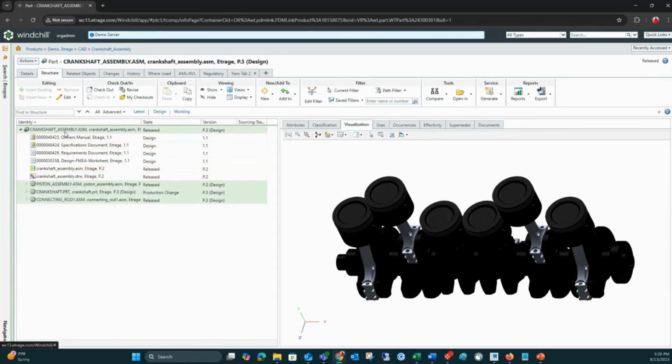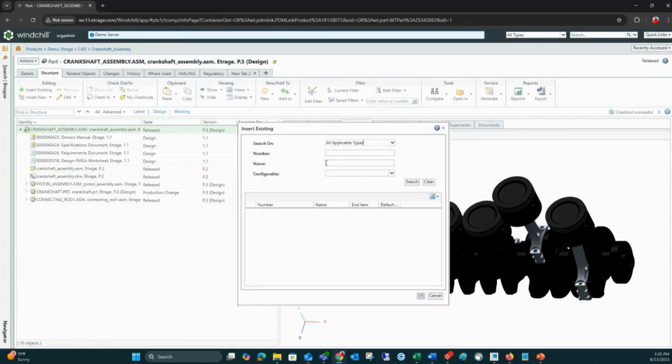And in this case, we're missing the software. So if I need to add the software component for this particular bill of material, I can, without modifying or without touching the engineering data, so the Creo model. So I can go in and say, all right, I would like to add in here a software part.